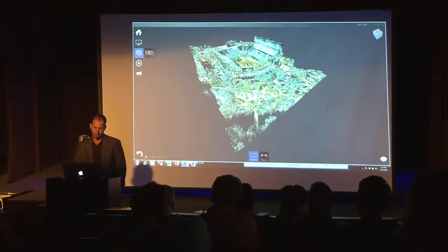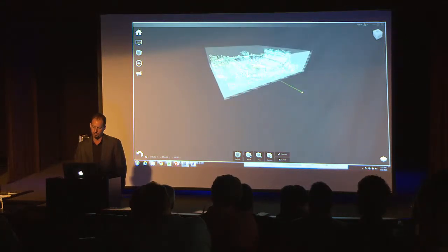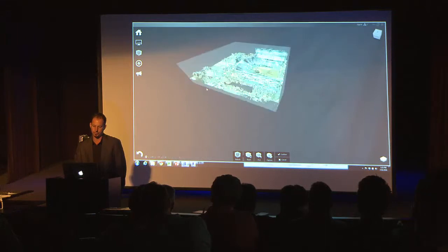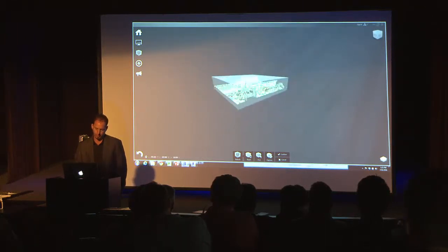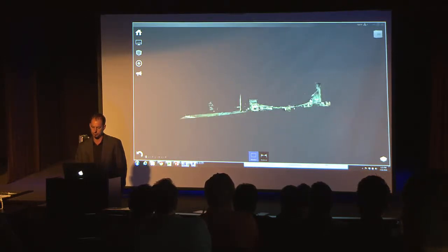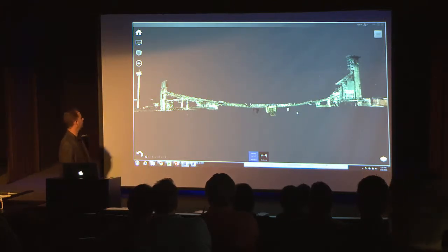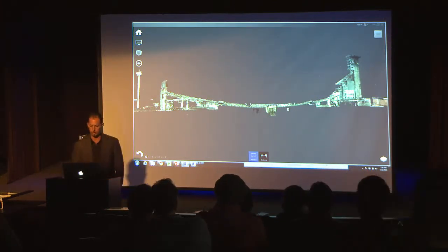Okay. Throw one back on there again, and let's go the other direction, right? What if we flip it through this way? So now we can create a cross section throughout a road, site, whatever we want, every 50 feet, every 20 feet, whatever we want to do here. And now we can start saving these, bring this into AutoCAD, narrow down to whatever is important to us, and then start drawing on that or start detailing whatever information we want, which is pretty cool as well.